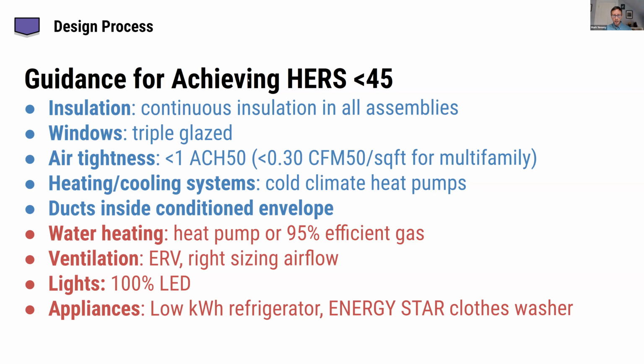You'll note I did not include electric resistance storage tank water heaters, kind of standard electric tank water heaters. Those would allow you to stick with the all electric path, but they have a pretty big penalty in terms of energy because whereas heat pumps get to move heat, electric tank water heaters are making heat with electricity, and that's just not a very efficient process. I often see things like a 5 to 8 HERS index penalty for going to an electric tank water heater compared to a heat pump or efficient gas water heater. So if you're going for a 45 HERS index, you may not have room for that hit.